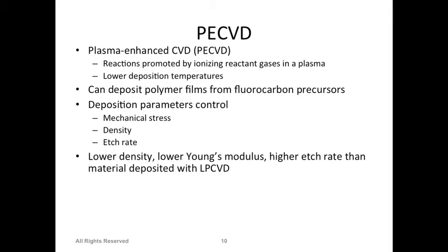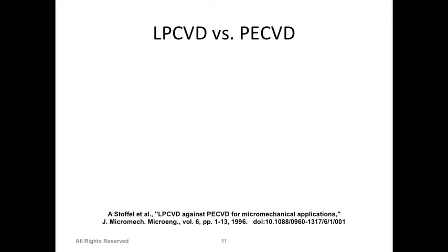Okay, so if I ask you which process is better, the answer would be based on where we are using it. If our core purpose is to deposit some material which should be very, very high quality, and there are no other conditions, I'll definitely go with LPCVD, because LPCVD gives you very good quality films, very dense and a good crystal form.